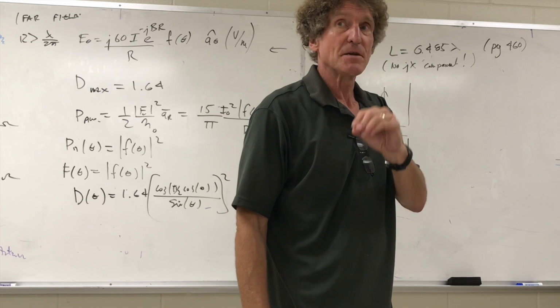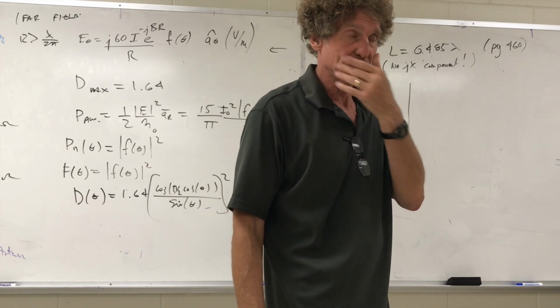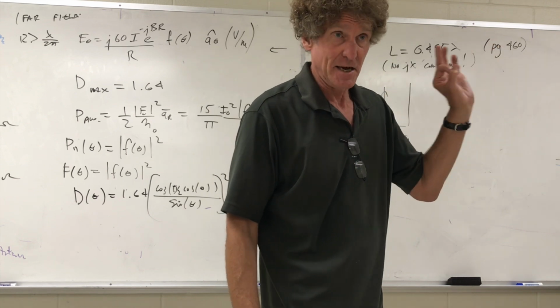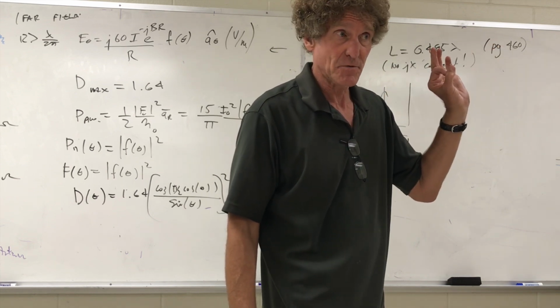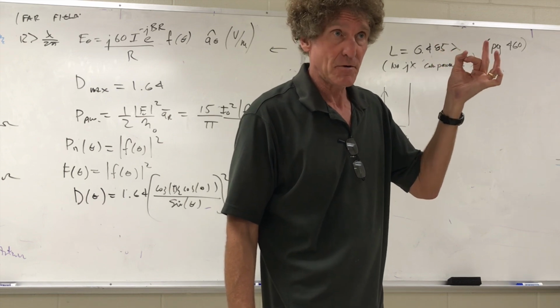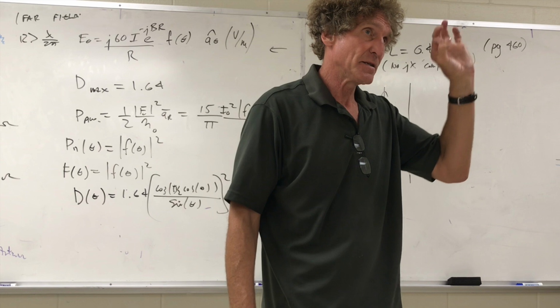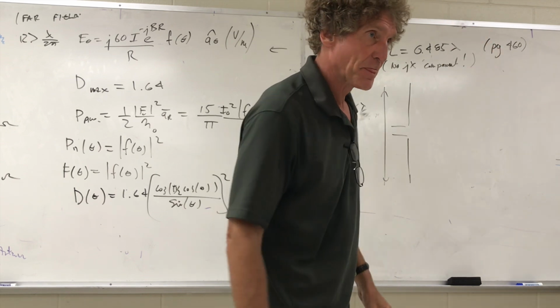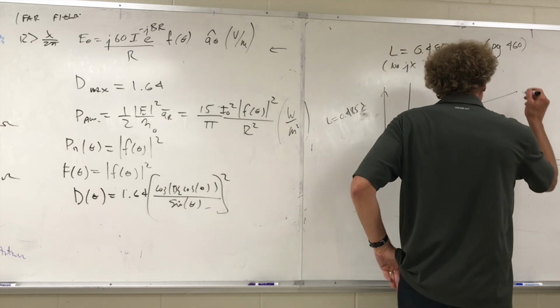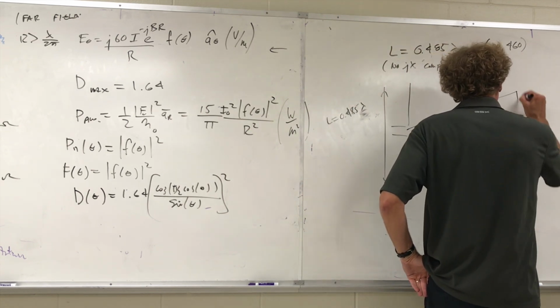From that voltage, we can figure out the current. And this is how power meters work. Like the Alabama Power, they never cut a line, but they can measure the actual current through it by finding the actual return current place or the feed current, and they wrap these little coils of wire around. They're called Rogowski coils.